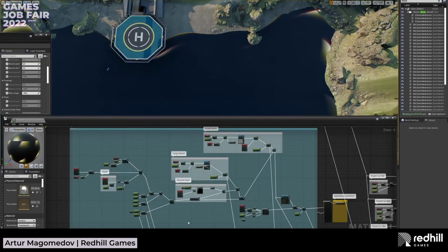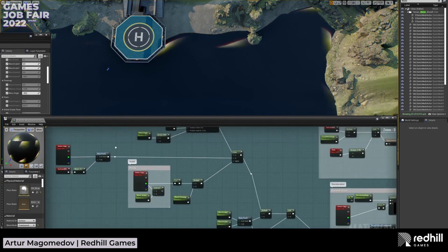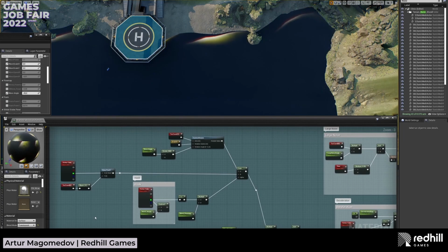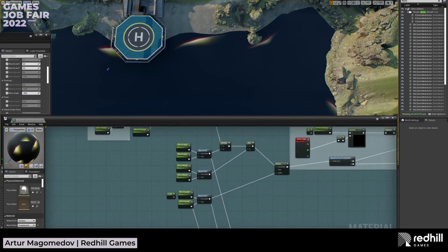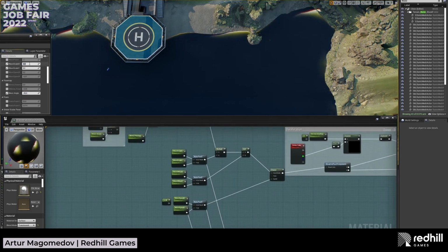And this is a forward wave. UV coordinates are a masked mix of flow map, regular texture coordinates rotated to the wind direction, and shore mask. Wind angle affects wave direction, and also waves are bent with the flow map. Here I have parametric control over the wave scale along X and Y of the texture. So we can make waves shorter or longer, narrower or wider.